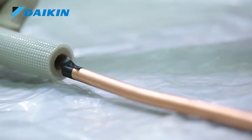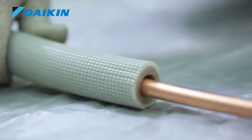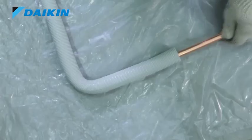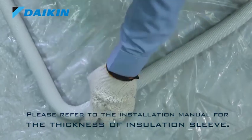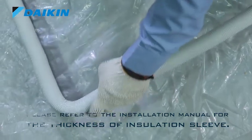As copper pipe is exposed to an open atmosphere, there will be loss of cooling effect. To avoid this, cover the pipe with the insulation sleeve. The thickness of this insulation sleeve should be as per the specification mentioned in the installation manual.